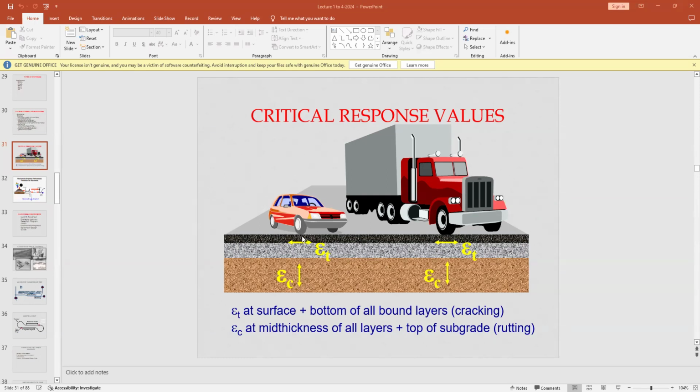We keep the asphalt bearing course at 2 inches, but you play with this depth. And the more the depth of asphalt, the more the depth of the pavement, the less the chances of failure of the asphalt concrete pavement. Automatically, it means that you have designed a pavement for more than an anticipated load.